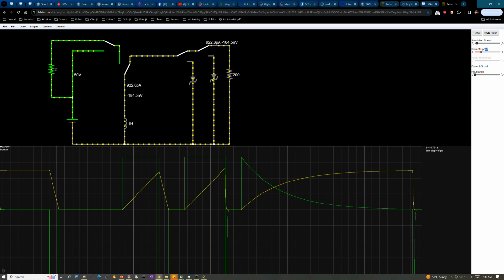It discharged at 100 times the voltage, but in 1/100th the time. You find that out if you do the math. It discharged a lot quicker than you charged it. So that's in essence how inductors more or less work, and the little magic trick they do by switching polarity is clearly demonstrated as well.